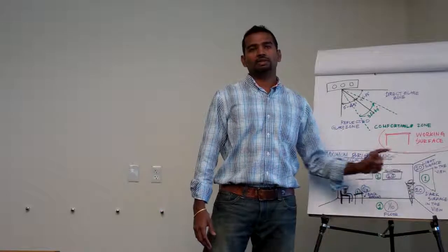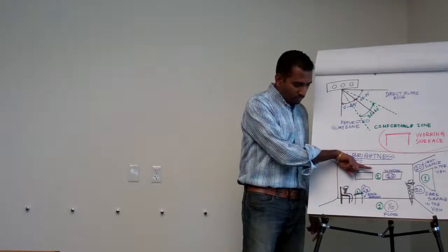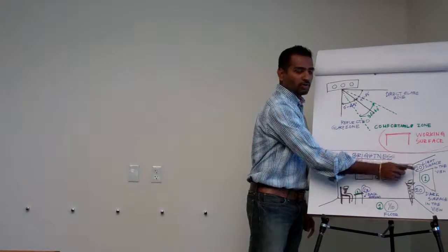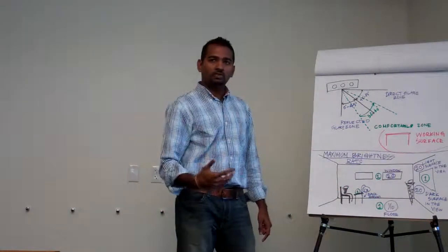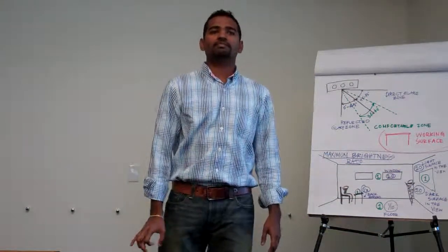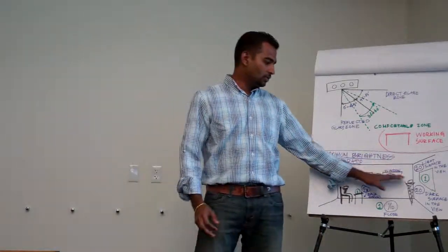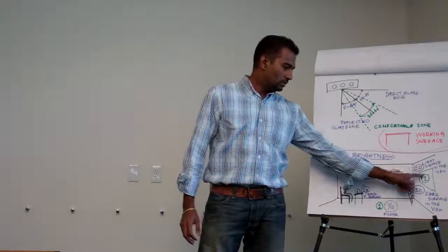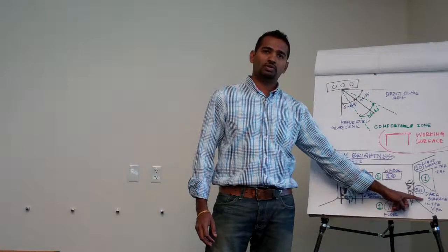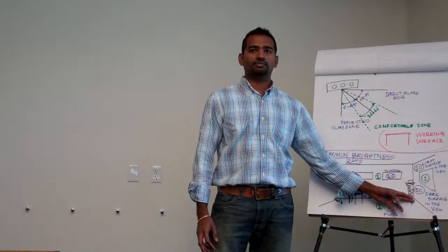So where does this help us? Say you have a window here, and it's 3 o'clock in the evening. Sun will penetrate through that window, and it will just wash this entire wall. If the amount of lumens that reflect off of this wall is above this 1 to 10 ratio, nobody can see a thing. So that tells us how much glare control we need. So it's very, very important. The moment you change that surface to a dark surface, you can go to a higher brightness ratio.